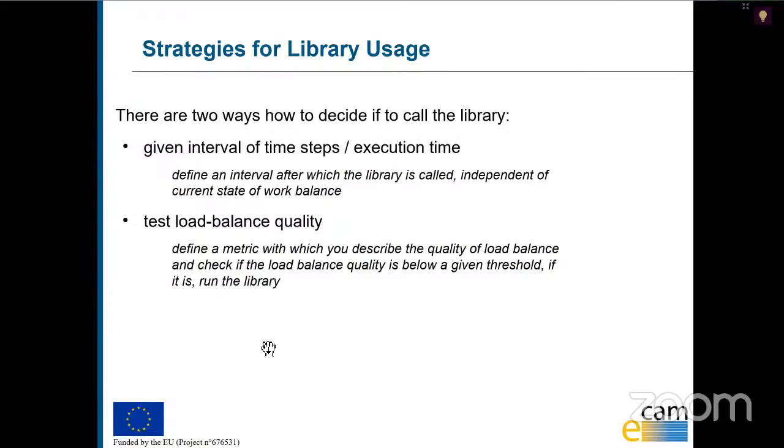So that, for example, you have 100 or 200 time steps after which you will run the library and update the domain geometry, or you would test, for example, after each step, the quality of your load balance in the system, and call the library if it is below some previously defined threshold.